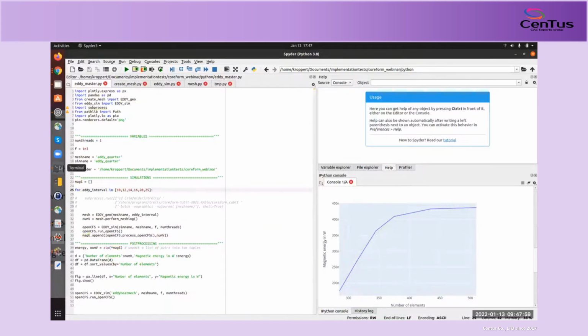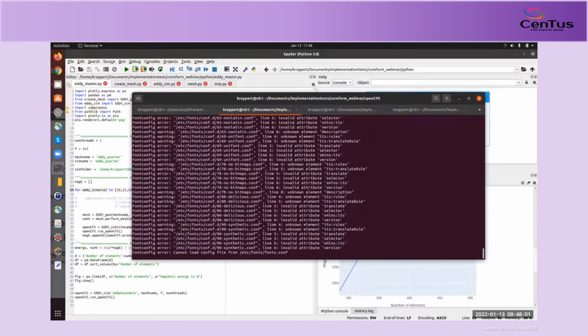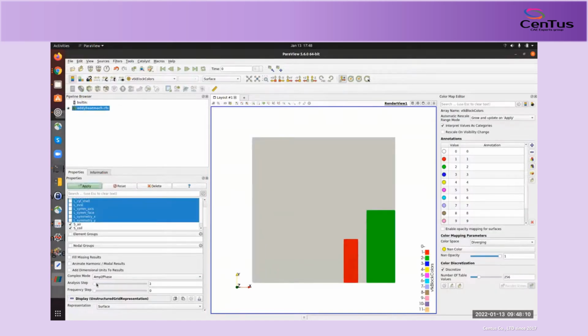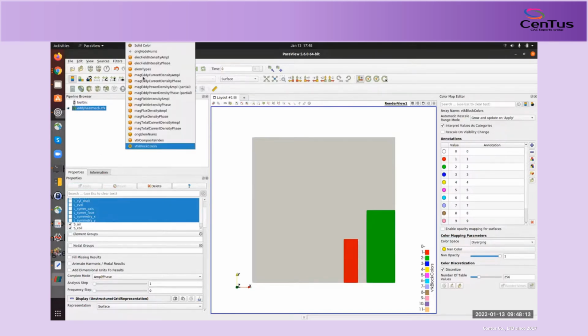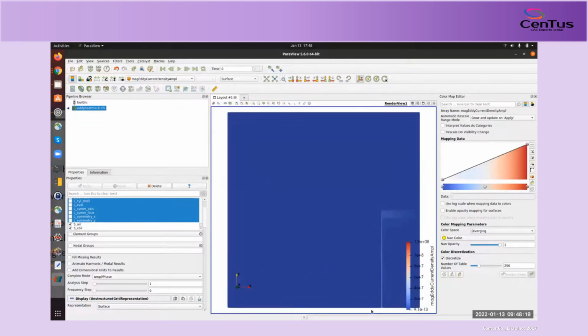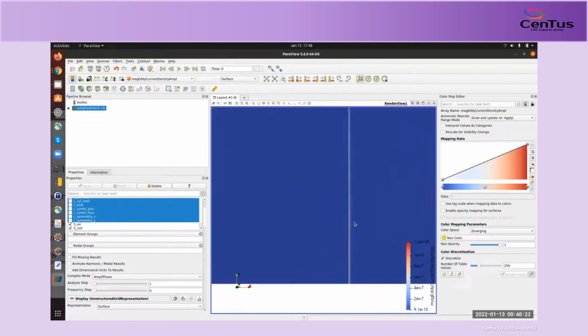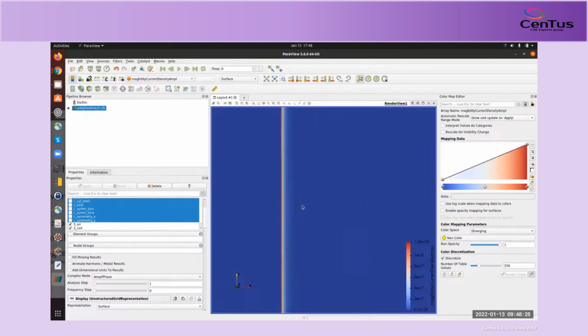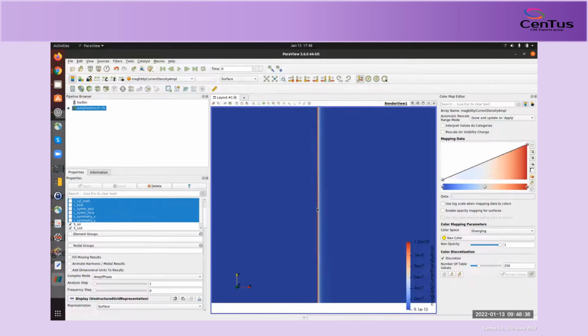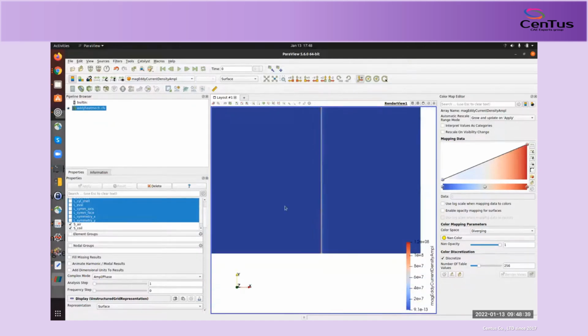And now let's have a look at the result, again, to see if we see any difference. Let's go to the magnetic simulation. Observe the eddy current density, and we see a totally different picture than before. So you really see the skin effect, so that the currents are really located at the very surface of the cylinder. And the higher the frequency gets, the smaller, or the narrower, this effect becomes.